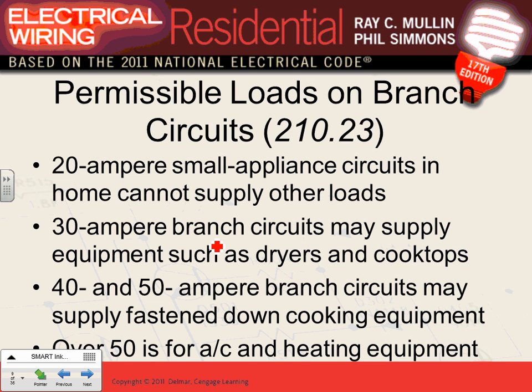Then we talked yesterday about where we use all these, and notoriously famous, guys, is where a 20 amp circuit in a dwelling is used. Anybody remember where? There are 2 small appliance circuits, 1 GFCI receptacle circuit for the bathroom, and 1 for the laundry. There are 4 of them required by code: 2 in the kitchen, 1 in the bathroom, 1 in the laundry. Done. These are required.